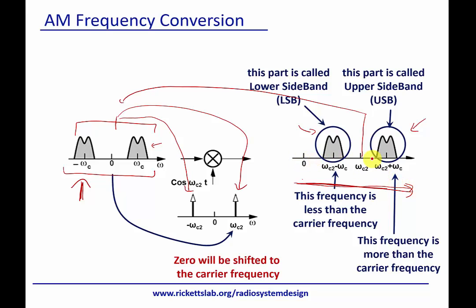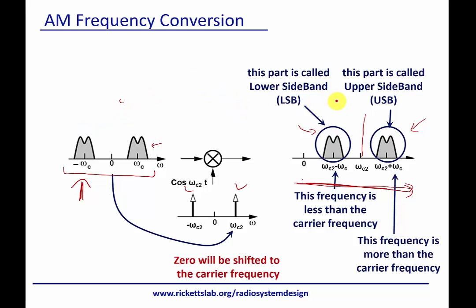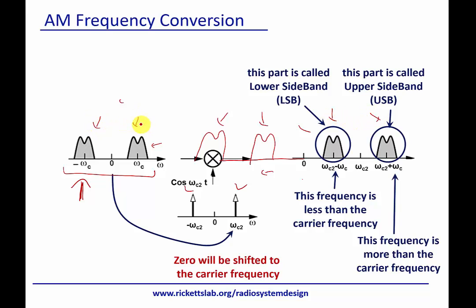So now we have these two signals, and if I were to plot this complete spectrum, just erase these real quick, and I were to extend this, we would have here in the negative. So we end up with 4 copies, where here we only had 2. And that's because each one of these gets a copy of what's there. So this is just a brief definition of a lower sideband and upper sideband, and it has to do with this center frequency when we do up conversions.